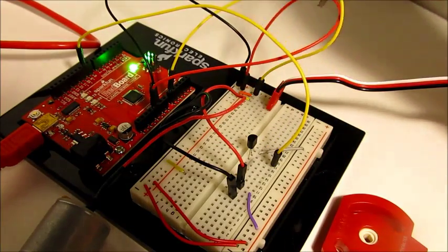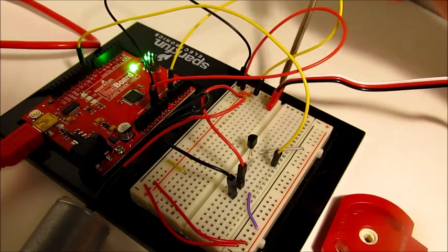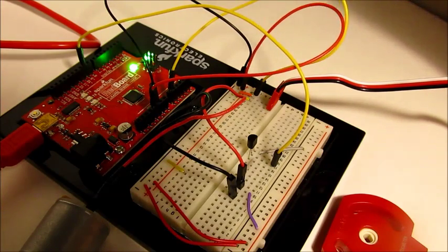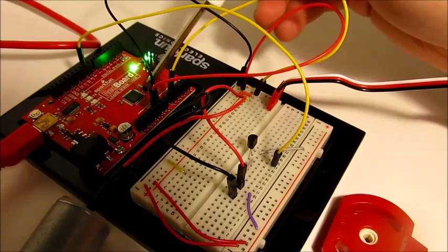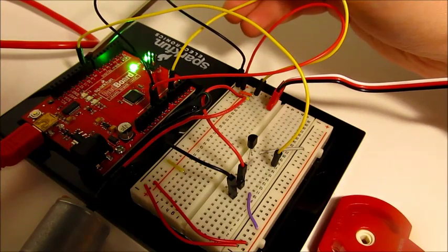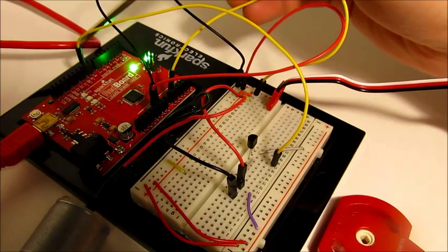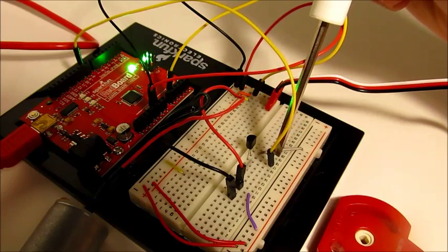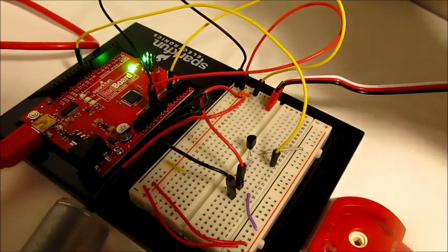The power comes in through the power bus, then powers the switch. There's a signal wire coming from the potentiometer going to analog pin 0. This then does the logic using the programming on the board, and comes out through analog write pin 9 using pulse width modulation to have an analog signal, which then goes into the transistor and is transmitted out to the motor as various voltage values.